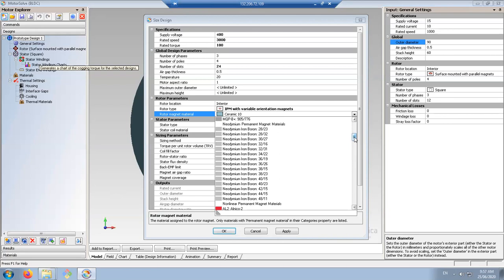For example, in high temperature applications, let's say aerospace applications, when the temperature goes up to, I don't know, 300-400 degrees, most probably you don't really want to use permanent magnets, especially the conventional ones, because they can get demagnetized easily at high temperatures. So those are the points that you need to take into account.